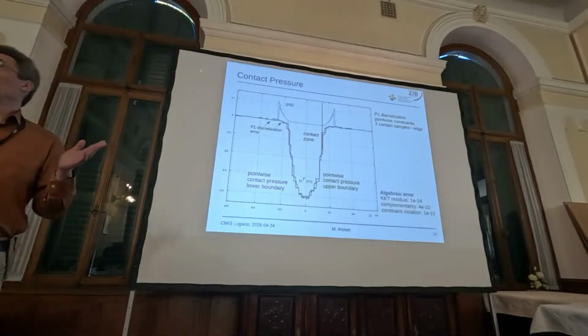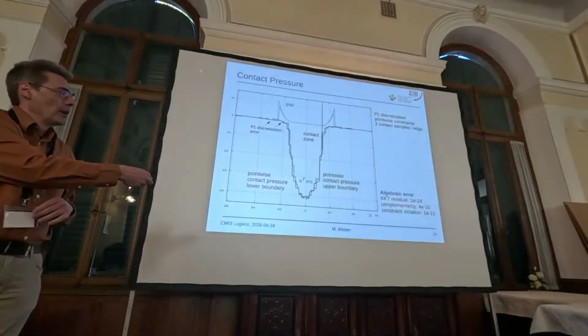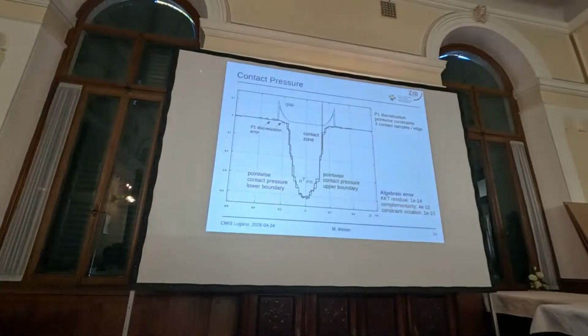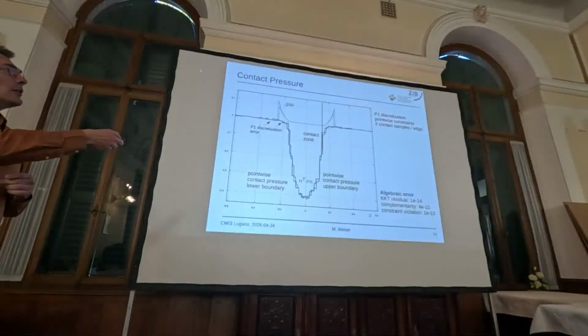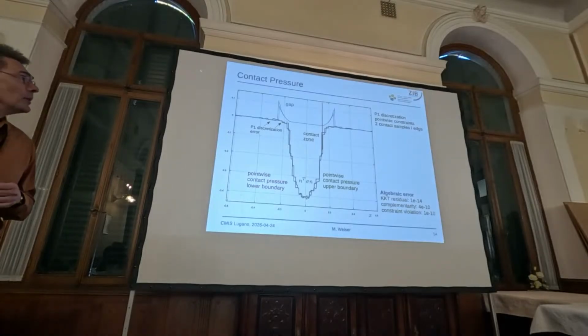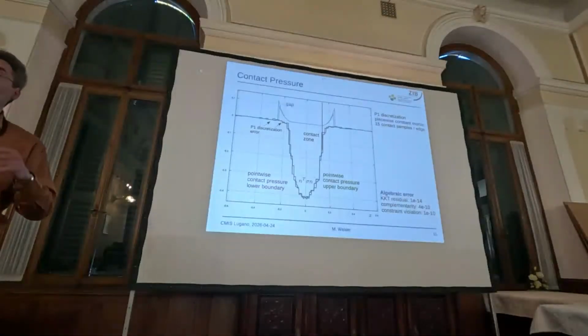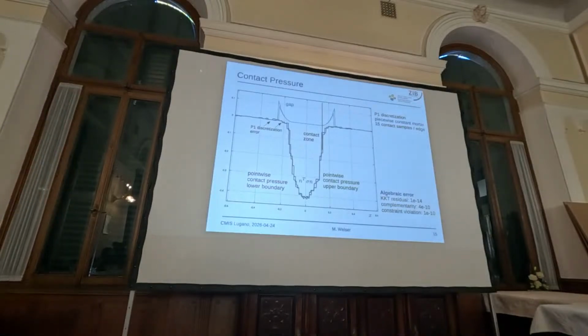One reason could be the solver, but actually, no, the algebraic error is quite small, so the residual is quite small. The solver does its job. It could be the contact discretization. So let's change this from 2 contact samples per edge to 15, and then again look at a mortar discretization with this piecewise constant mortar basis function.